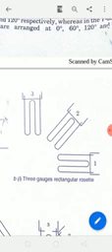The second one, in the rectangular gauges, is the 3 gauge rectangular rosette. One is placed in the horizontal direction, another placed in the vertical direction, and another placed in between, that is at 45 degrees. We call this a 3 gauge rectangular rosette. So what is the angle of each? Gauge 1 is in the horizontal direction, so the angle is 0 degrees. Gauge 2 is at 45 degrees, and gauge 3 is at 90 degrees, right?